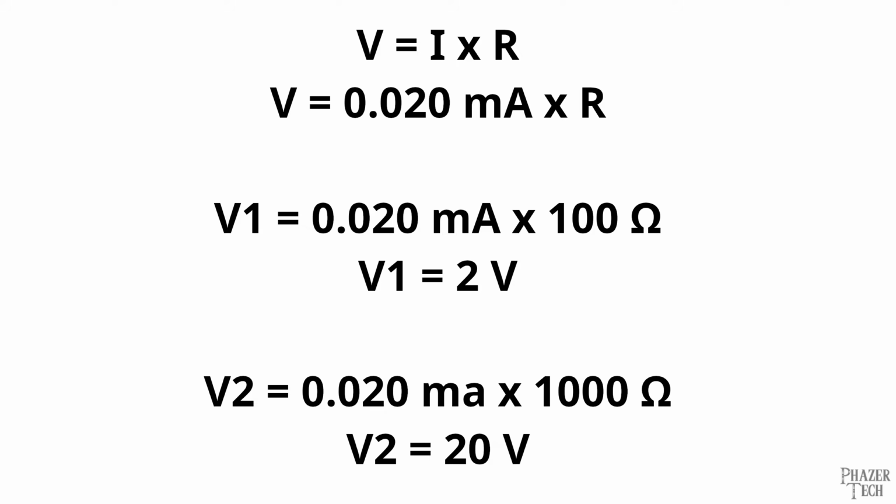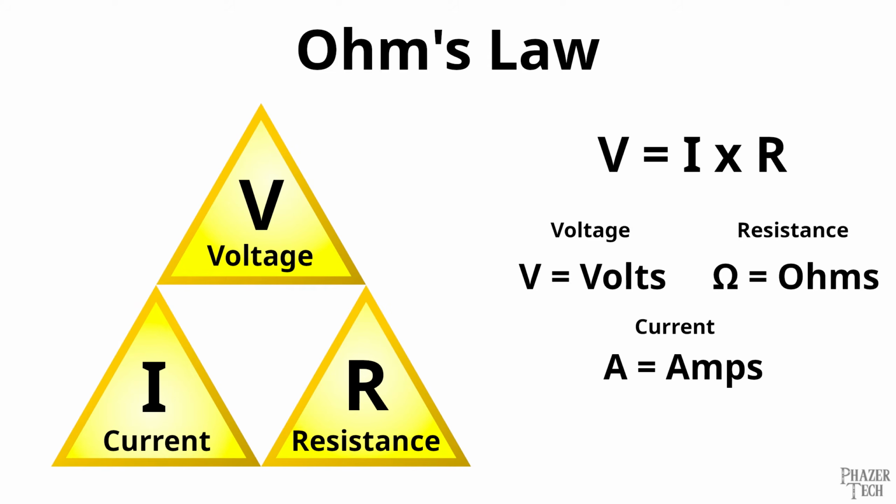So from this point of view, the resistor isn't limiting the current, but is creating a voltage drop in the circuit. It brings us back to the point about Ohm's law that I really wanted to reinforce in the first video. There is an intrinsic relationship between the voltage, current, and resistance, and changing one of them has an effect on the others. So while a resistor does resist the current going through it, it also has an effect on the voltage and creates a voltage drop across itself.